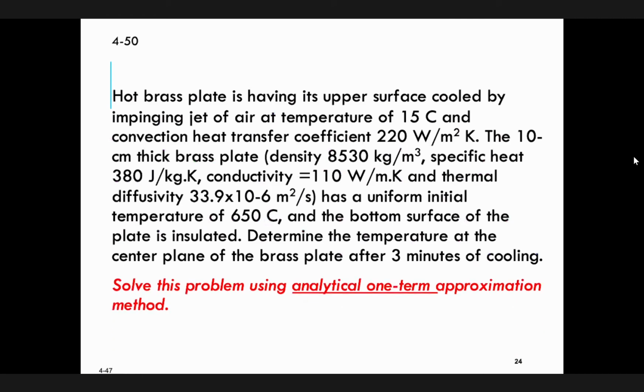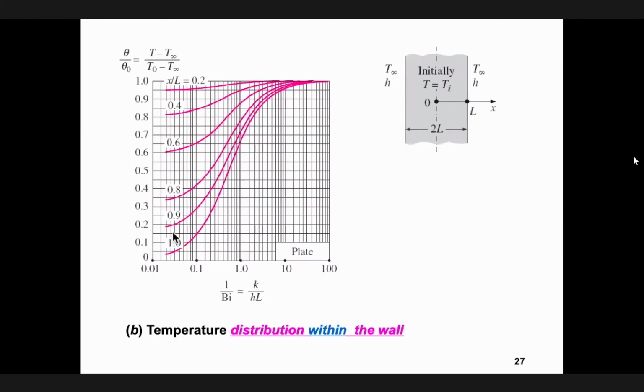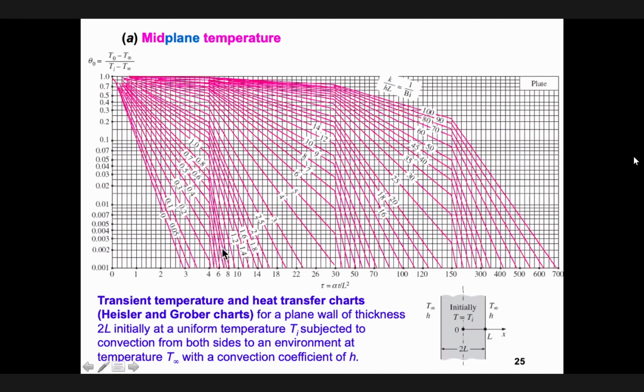Just go to the plot here. For example, for the wall, they solved that differential equation, and this gave you the axis and the temperature distribution, okay? The temperature here is T0. It means the temperature at the center, not at any point. It is the temperature at the center of the wall at this point.